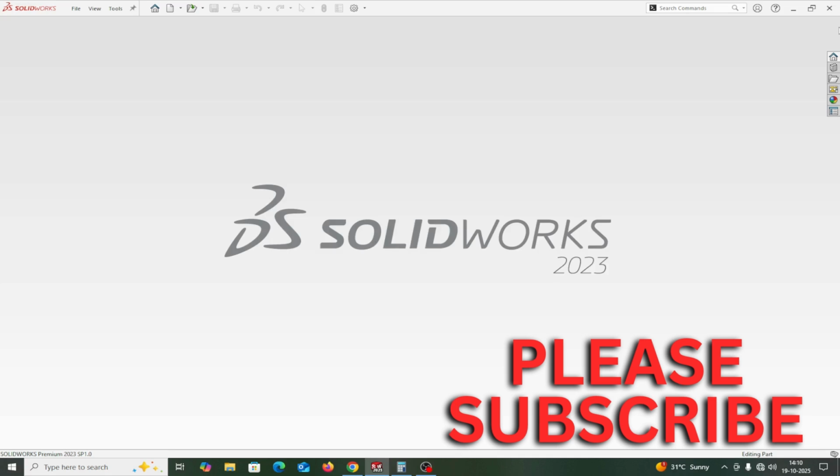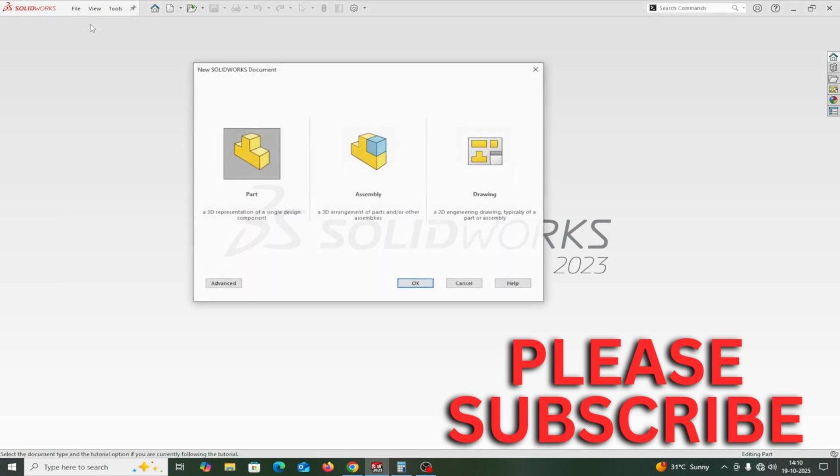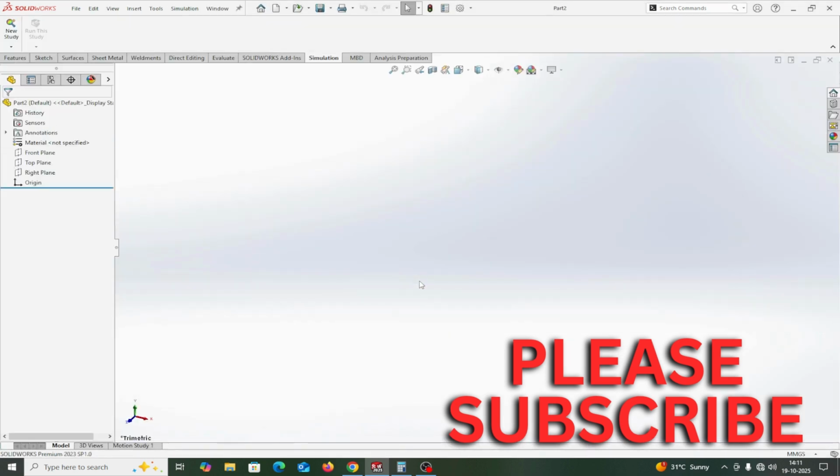Hello everyone. In this exercise of SolidWorks, we will study the displacement or deflection in a cantilever type beam. Okay, let's start. File, new, part. Part is the default template. There are three environments: part, assembly, and drawing environment. Part is the default environment. Select OK.